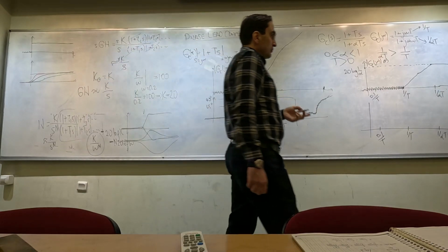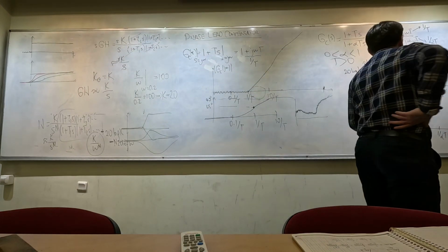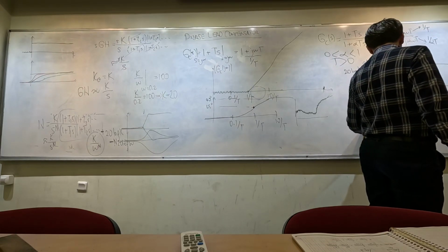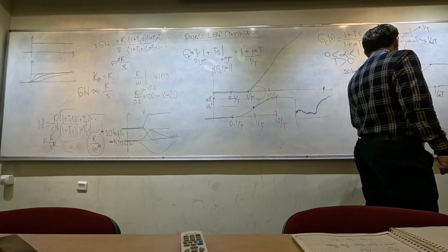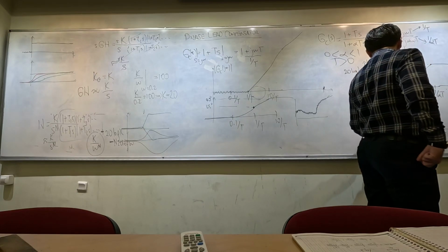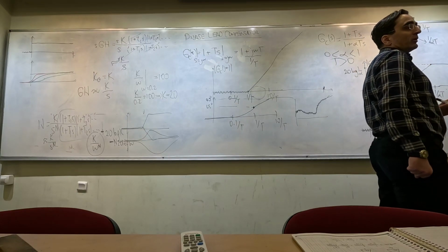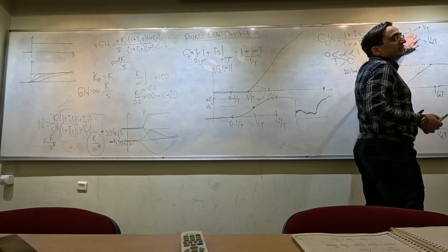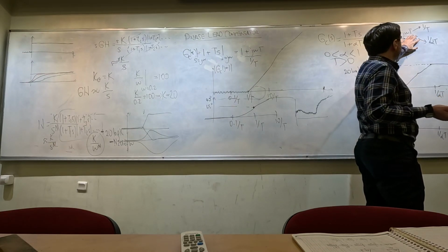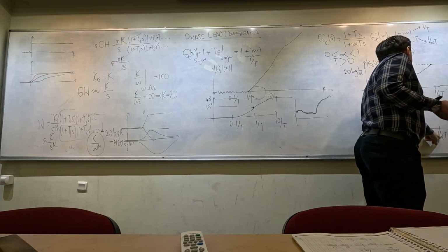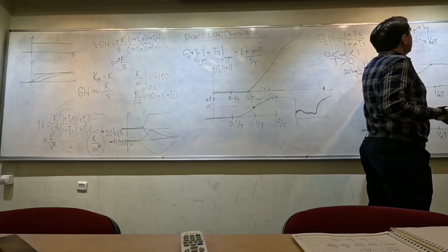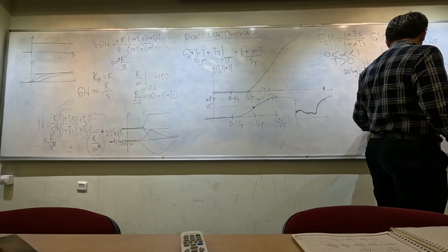What about the phase lead compensator? In that case, the phase is going to be 0 for low frequencies. When we go over the frequency 0.1 over T, the pole term would still bring us 0 phase, because we are still not close to the corner frequency of the pole term. So the zero is going to start increasing the phase.